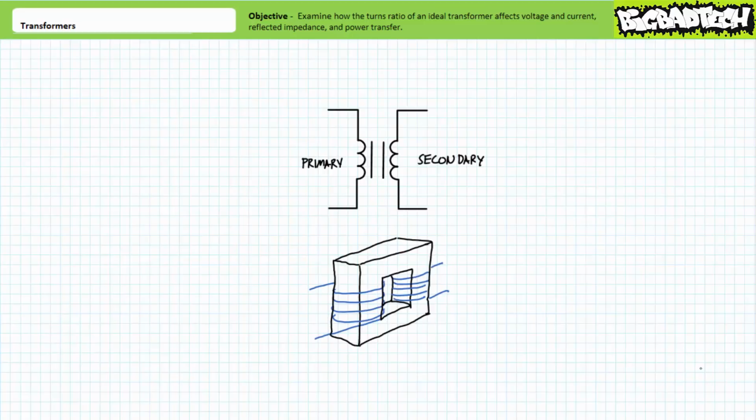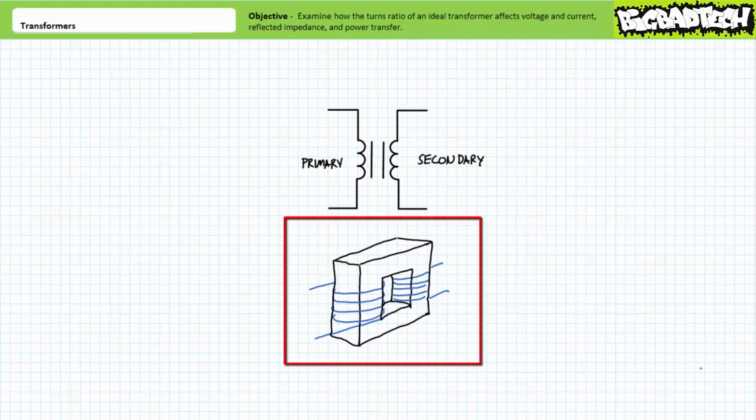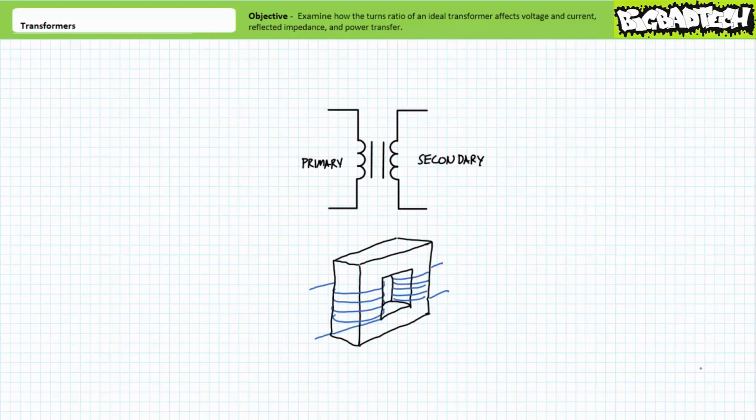Although construction differences vary from manufacturer to manufacturer in use, a general diagram of an iron core transformer looks something like this. Imagine a ring-like structure of iron around which is wrapped the insulated coils of the primary and secondary windings. Any magnetic field generated by the two windings, rather than wandering off and getting into trouble, is instead confined to the iron core, thereby ensuring the two windings remain firmly magnetically coupled.